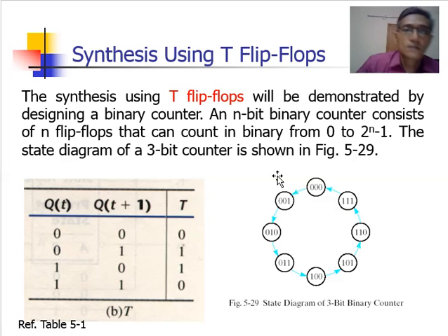Welcome friends. In this video lecture we will learn synthesis using T flip-flops. That is, synthesis of clocked sequential circuit using T flip-flops. So here we will take up an example of designing a 3-bit counter using T flip-flop. As we all know, a counter is a sequential circuit that counts through a specified sequence.